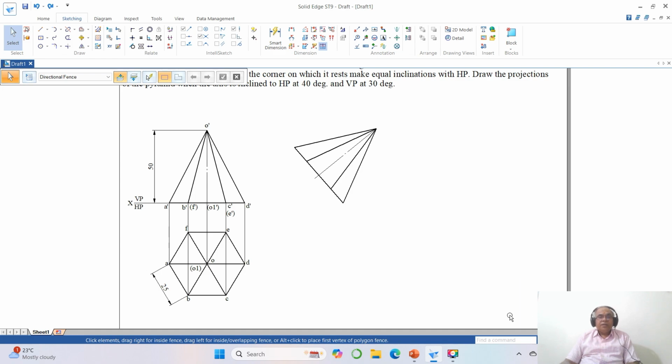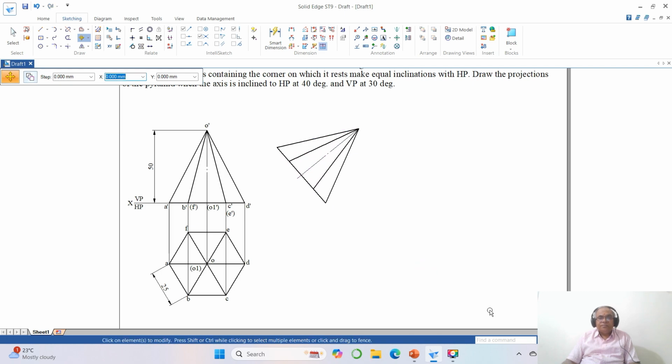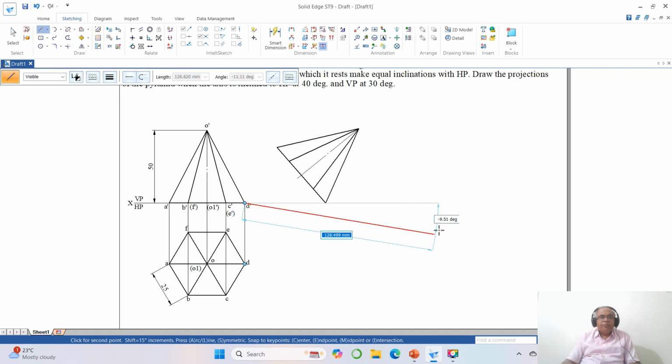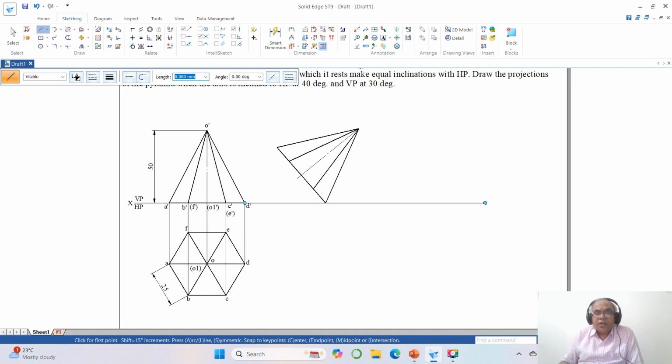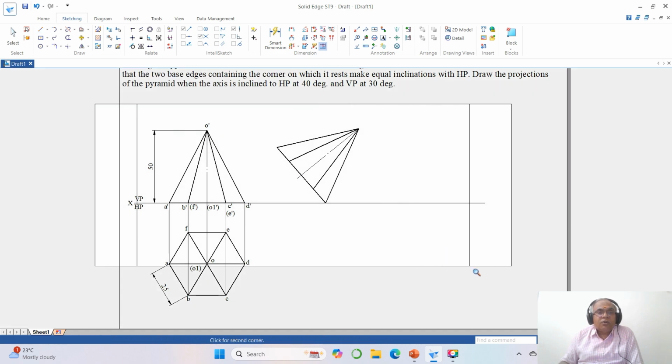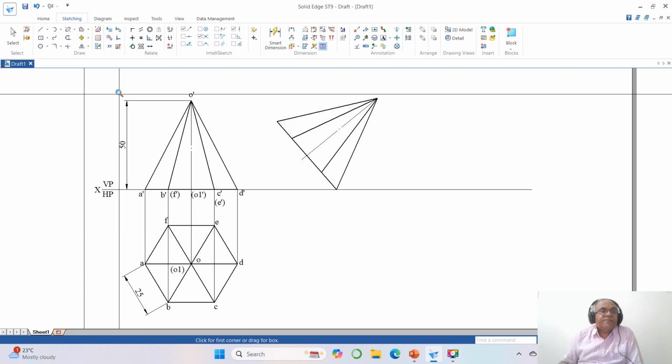So once you do that, now if you want, you take it at the same position, or you can move it inside. You go to move, select this and give the y displacement as 0. Now move it wherever you want. I want to move it a bit inside, you take it. Then go to line command, draw a line from end point to this. Okay, now you copy all these things to the second position, front view.